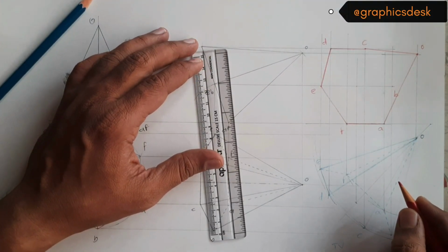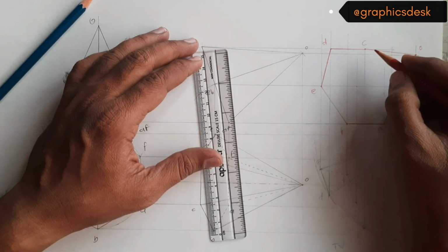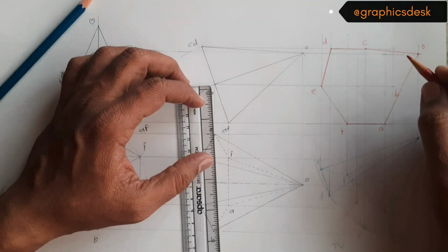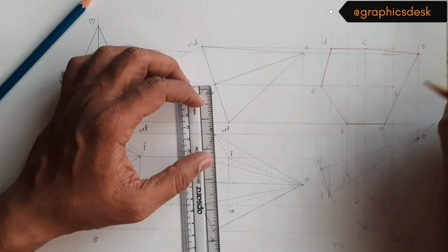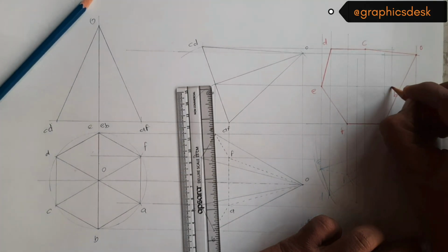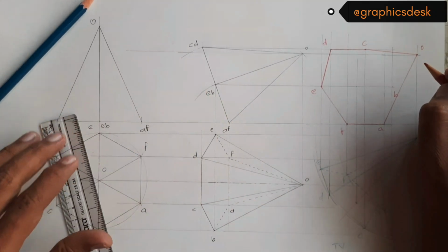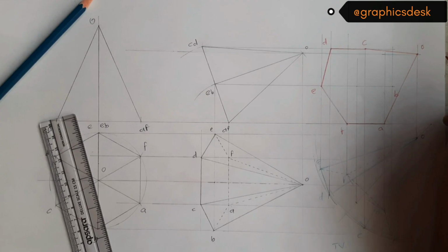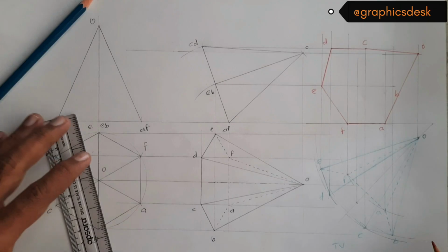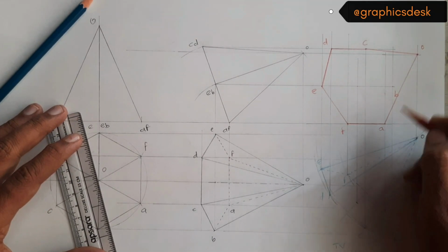Okay, the only point that is not connected is point B. Rest of all the points, including O, are on the periphery of the front view. So all the lines going through point B would be solid lines, because point B is near to the observer when we are talking about the front view. So all lines going from B would be solid lines.